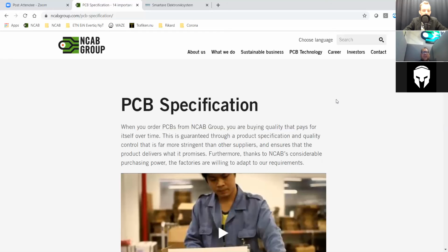And it's not saying that you should only use the simplest standard, but within each material or build-up material supplier, they have a big variation within their products. So they have maybe 20 different part numbers to do the same thing. And if you're using a very unique one, because that's the one you heard of, then that could drive unnecessary cost and make you have less availability. Not so many factories can do that, or there will be a long lead time because they don't have it in their warehouse. So using standard materials instead of unique materials is also a good thing to think of in your specification.